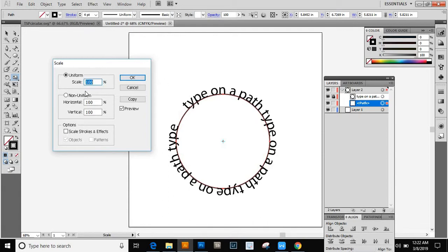We're going to scale it down some. Let's scale it down to 80. You're going to type in 80, then click somewhere neutral. Boom. That actually previews where the circle would be.